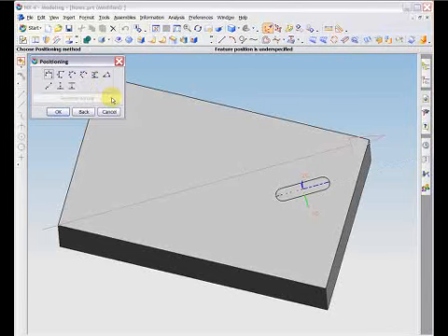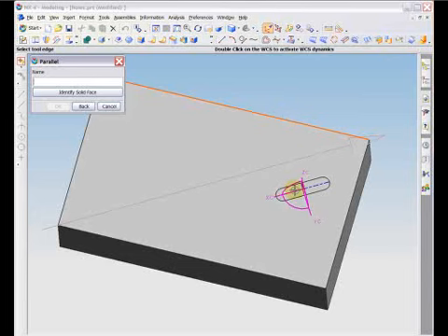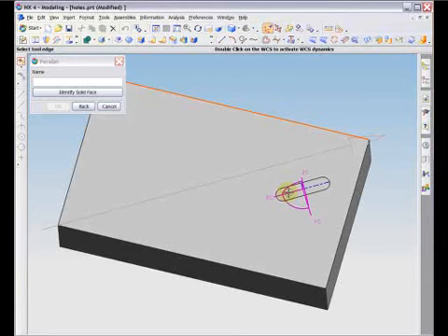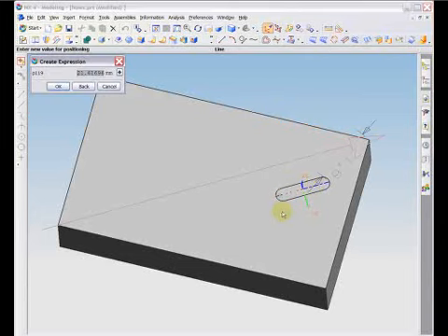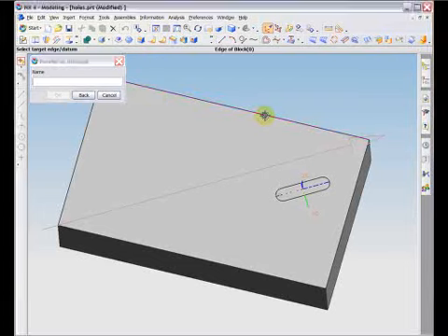Another option is to use the parallel constraint, which will specify the distance between 2 points measured parallel to the work plane. If you choose edges rather than points, the endpoint nearest the pick point is selected. You may also select parallel at a distance, which constrains the selected edges to be parallel and a set distance apart.